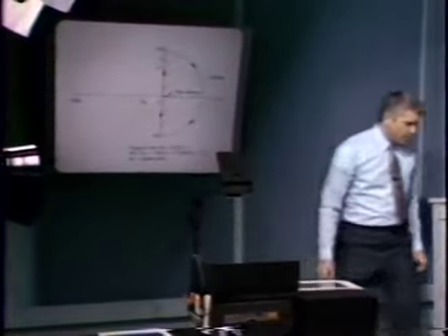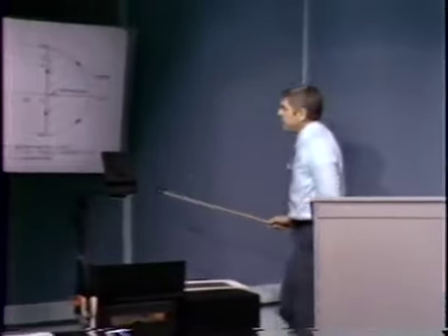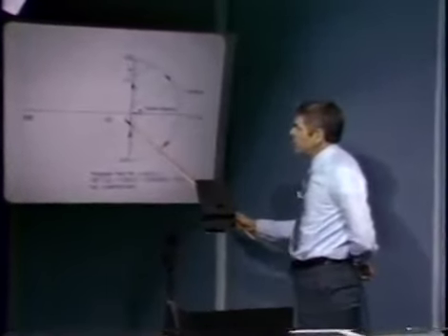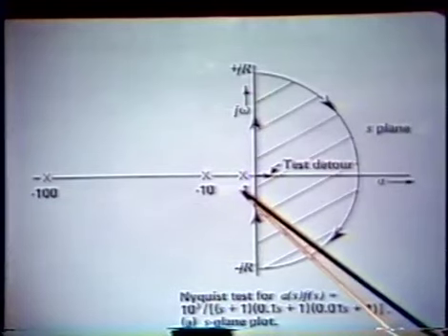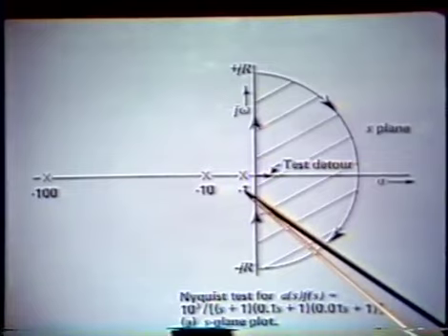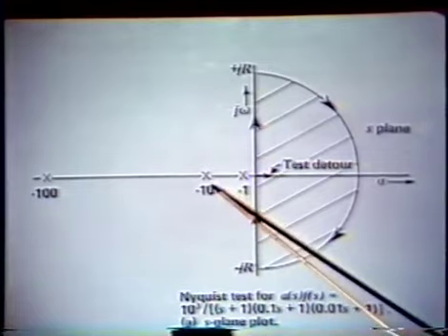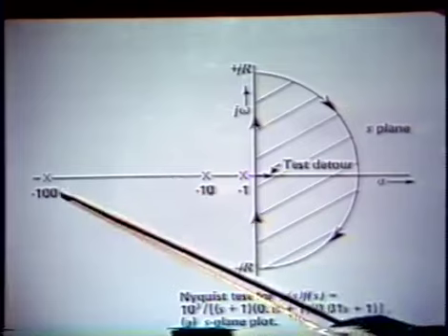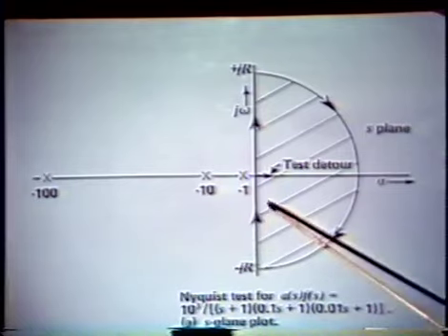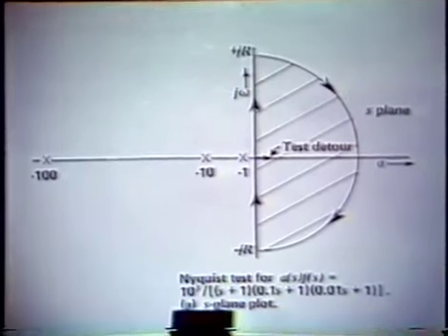Here we show that situation. In fact, to aid our construction in the S-plane, while we show the three loop transmission poles, we'd also probably show zeros to help ourselves if any existed. Here we have a pole at minus 1, a pole at minus 10, a third pole at S equals minus 100. And here's the Nyquist contour that we're interested in.